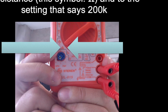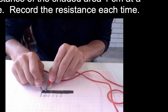The multimeter has different settings, right? Since we're working with something that is pretty highly resistive, we'd set it to something that has a really high resistance rating, 200,000 ohms. Then we're going to use our multimeter to measure the resistance across different lengths of this graphite. Right, so as we increase the length, we're increasing the distance that our electrons or our current would be traveling through this graphite strip. So as we're increasing the length, we should also see an increase in resistance each time.